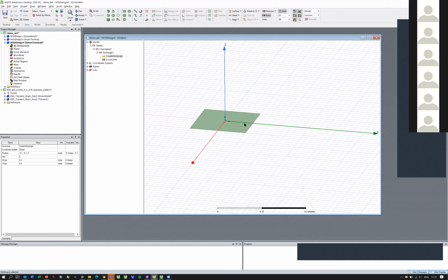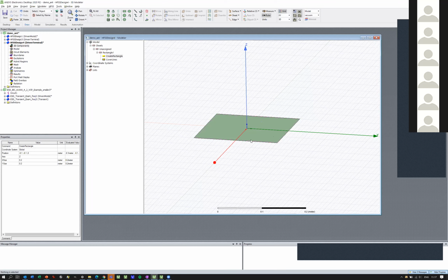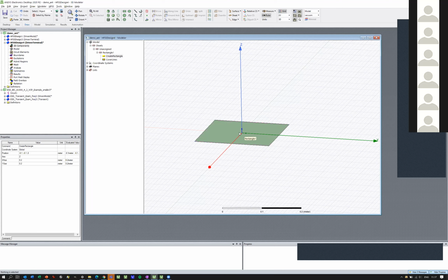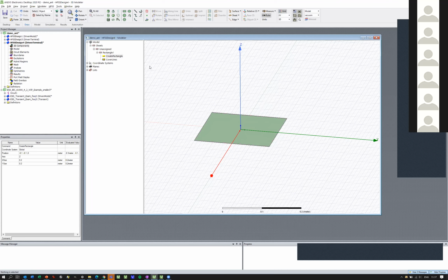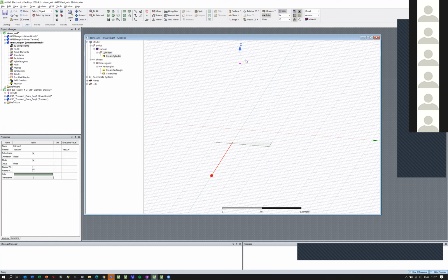So now let's do a simple monopole antenna and see how to simulate a simple antenna system. I will take the cylinder drawing tool. It will snap on the middle edges automatically, so it's easy to find the point. I'm working on this layer now, which is my main global coordinate system. I will click on that and just draw any size.